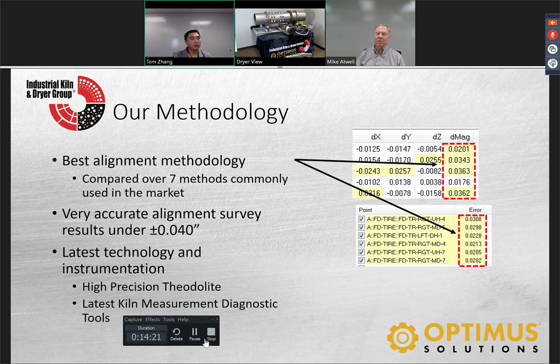But the whole way through, we have to go back and check the control points prior to shooting the unit. And when we get done shooting the unit at that station, we check it again before we actually tear it down and remove it. That way, if something happened to the theodolite where it was at, if it got moved or shifted while you're taking your shots, and you shoot your checkpoints again, and it's out of the calibration of where it has to be held, we stop and redo all those shots from that location.